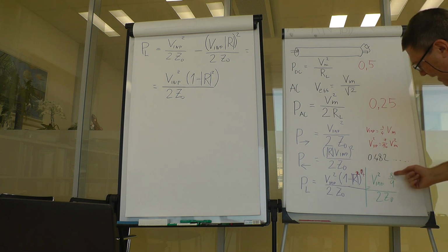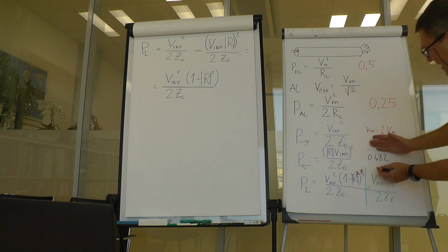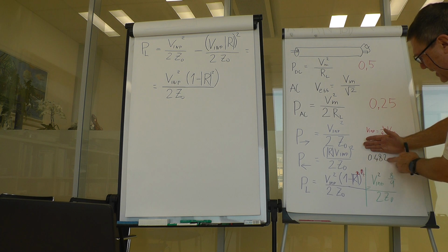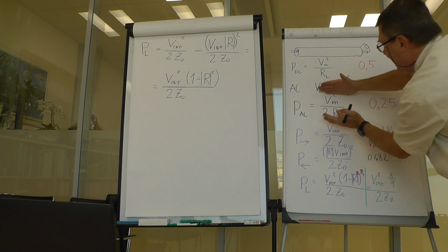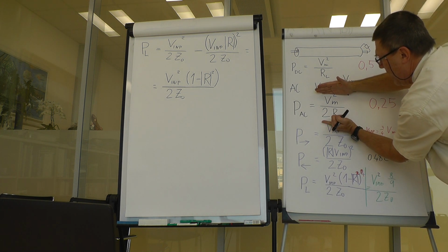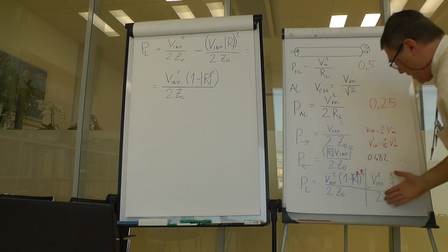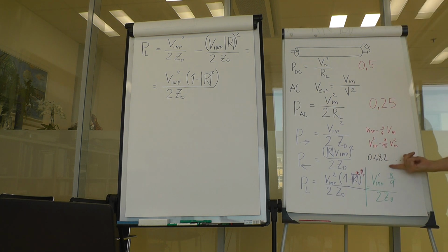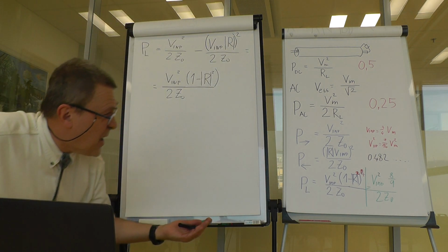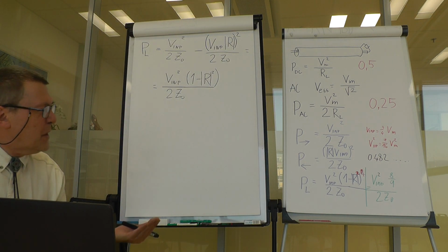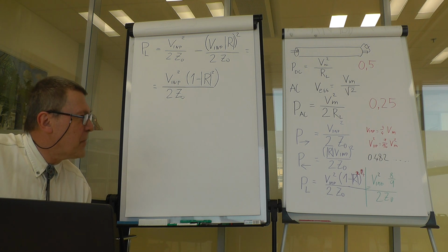We have to multiply it by 8/9, and that's the resulting number. So this is the ratio that decreases the maximum power due to standing waves. So this is a decrease against this value for AC current. So that would be again halving the power that is delivered to the load for the case of a 100 ohm load terminating a 50 ohm cable.